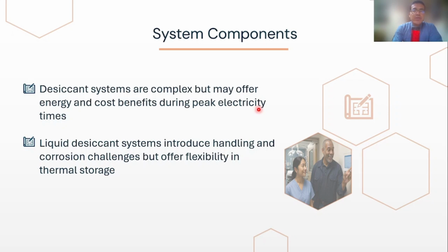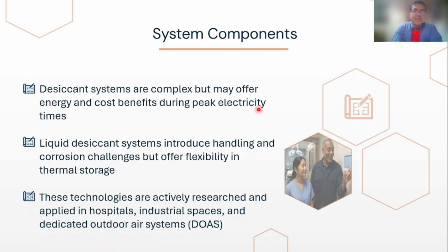The salt solutions can be corrosive, and tiny droplets may escape into the air stream. For this reason, filters or demisters are necessary, and careful material selection is important. Despite these complexities, both solid and liquid systems continue to see interest, particularly in applications like hospitals and industrial buildings where humidity control is critical, or in the DOAS, where fresh air must be dehumidified independently from the recirculated air.